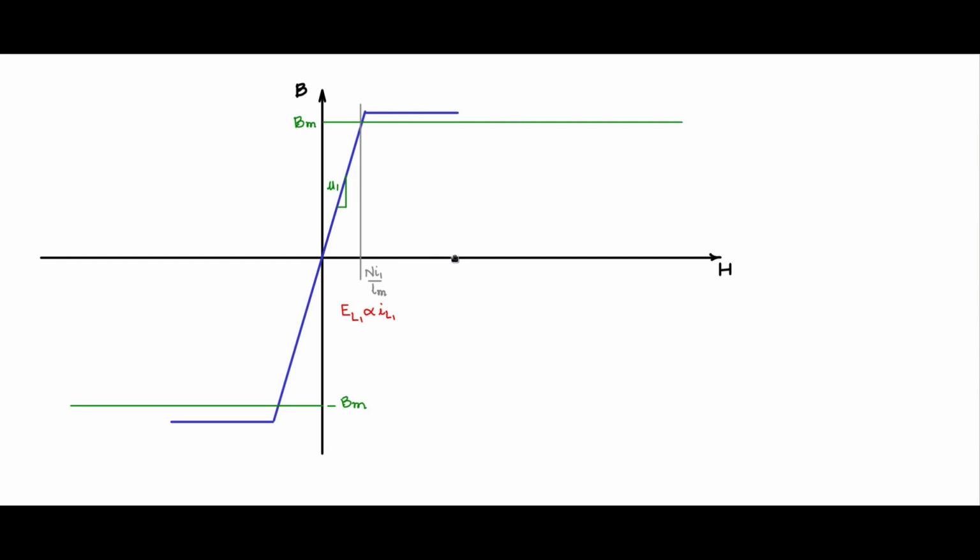So how do you still keep the flux in operation without saturating the core and still be able to store larger energy? So let us see what happens when you reduce the permeability mu. Let me draw another line here, which has a lower slope, and this intercept here. You see, for the same BM, the intercept for this lower permeability core, where mu1 is greater than mu2, is N I2 by Lm.